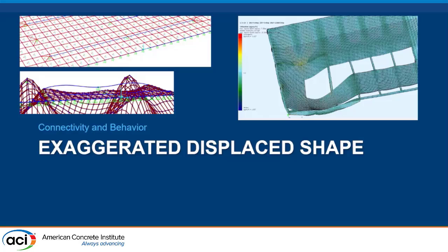and that really can help you identify issues with your design. Hey, wait a minute, do we need another beam here? What are we doing? Why is this beam twisting? Do we want it to twist? Have we designed for it to twist? Have we put the torsional reinforcement in this girder to allow it to twist? Because the model doesn't know these things. It's going to do whatever the restraint conditions that you've applied to it. Now, you as a designer need to think through that.